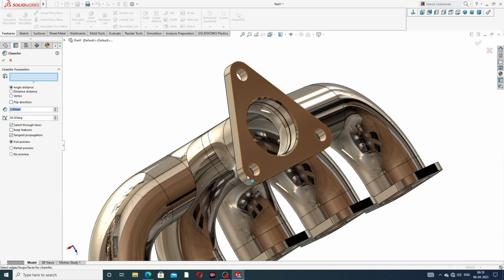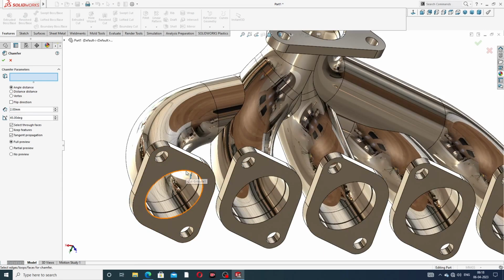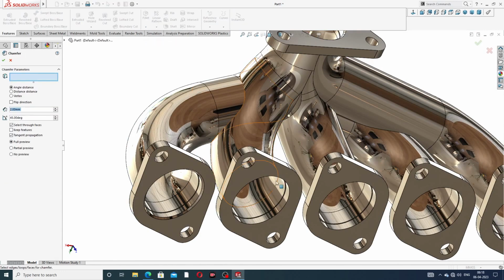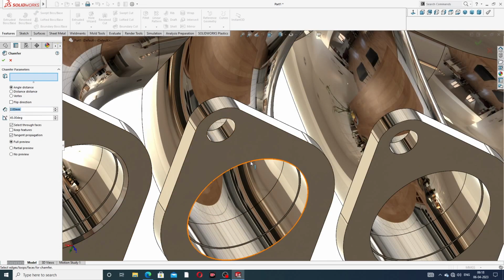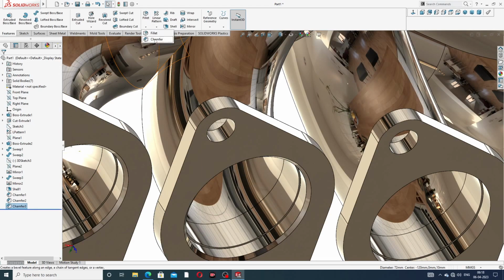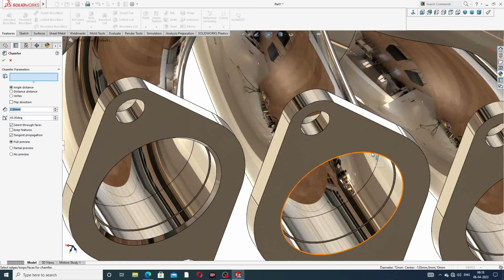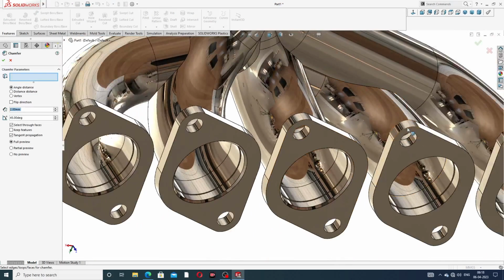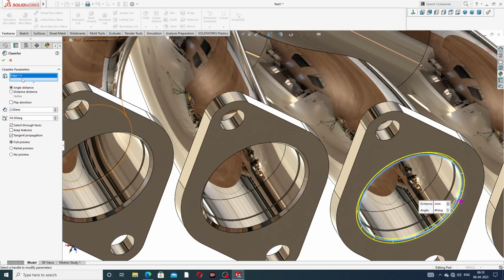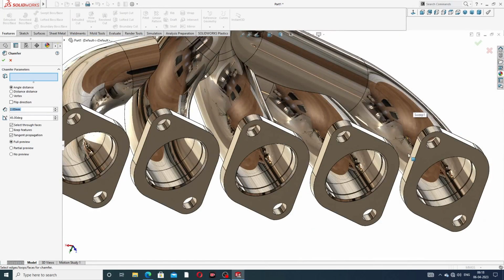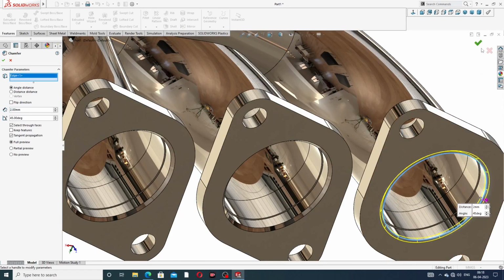Also select a chamfer of 2 millimeter and 45-degree angle, and this, not multiple, select here. Okay, the chamfer is also selected here, click OK and also select this. Okay, and next last is a 2 millimeter 45-degree angle, select here this and click OK.